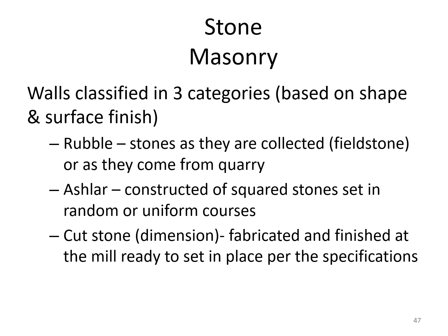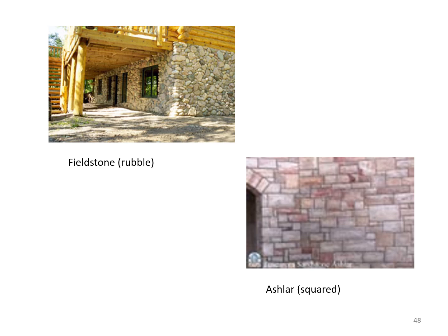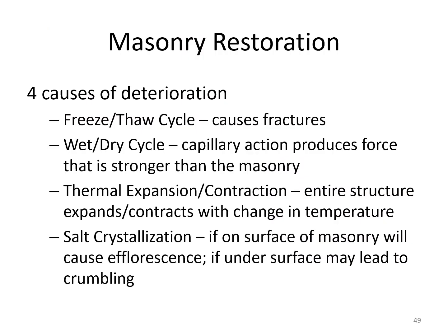Then you have, of course, the cut stones, which are dimensionally cut. Those are like bricks. They're milled and ready. They come in common sizes, like the bricks, 4-inch by 4-inch by 10-inch long, and those are easier to place, of course. But most stone masonry is done on the odd shapes and sizes. So here are some of those odd shapes and sizes. The rubble type, using regular field stone, taken right out from the earth. Then you have the ashlar type, where you have different sizes. They've been cut a bit, but they're all of different sizes, different cuts, as you can see.